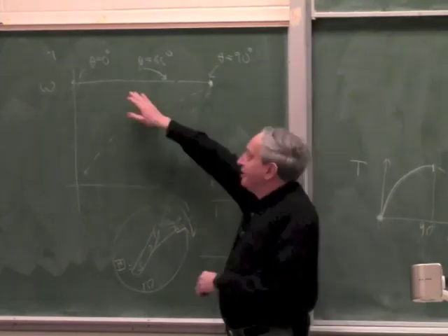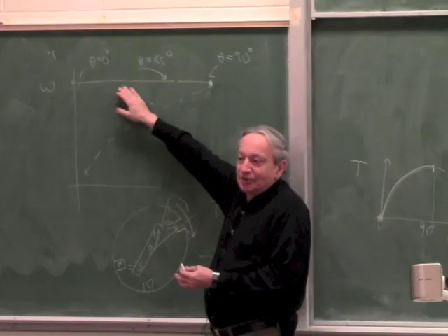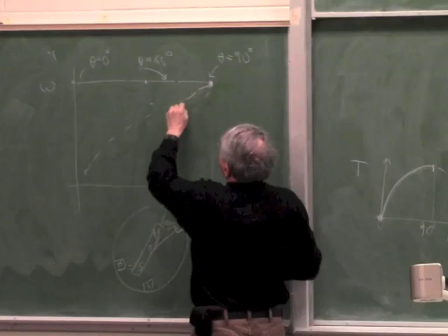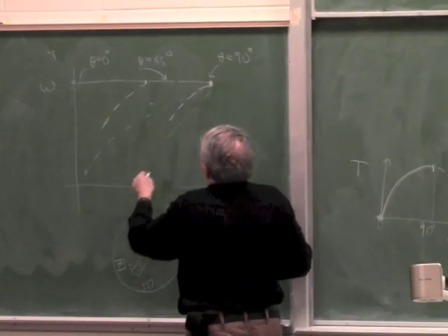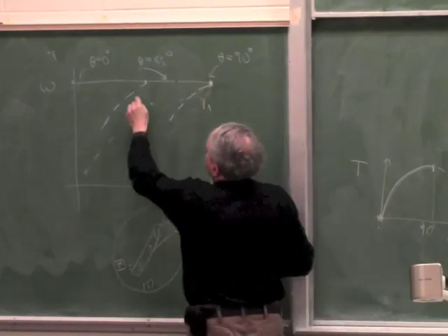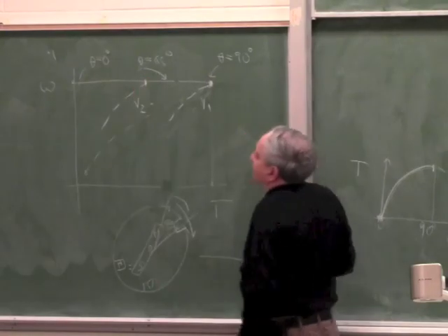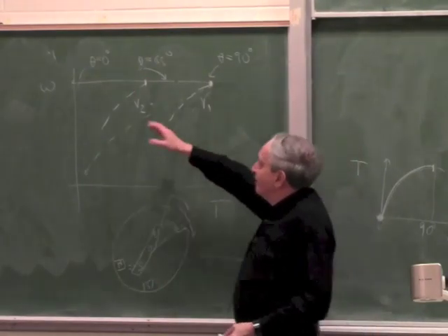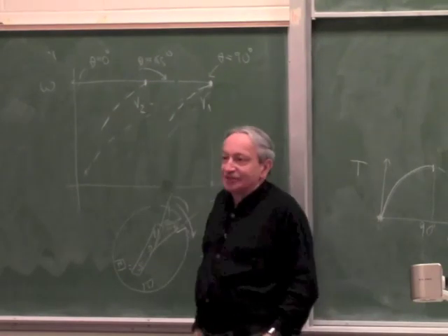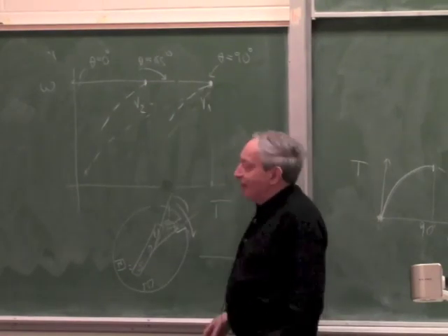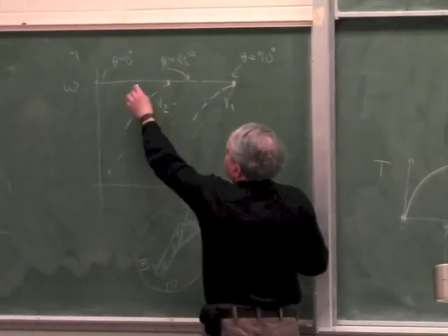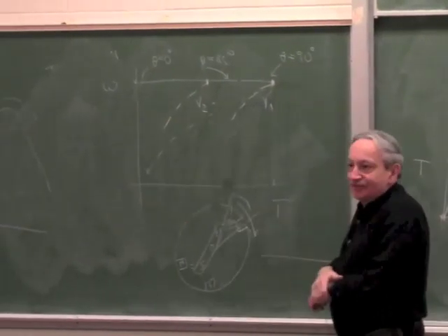Exactly, because the speed cannot change. It's a synchronous motor. All that happens, it collapses here. So instead of collapsing here, it collapses here. So this will be V1, this will be V2, because it can't generate any more torque, because there's less current, less torque. So the power angle winds up faster and it collapses. Okay? So it doesn't really have a family of curves. It just reaches a different torque and collapses.